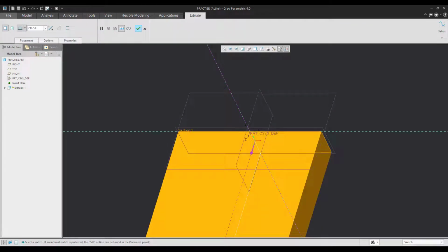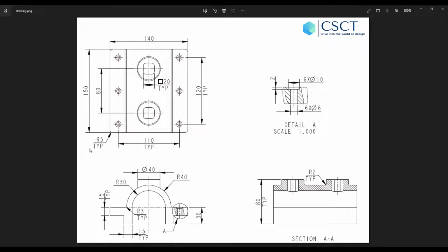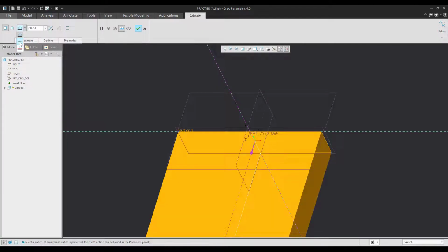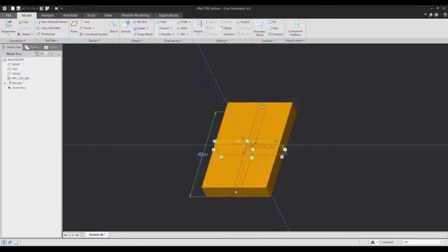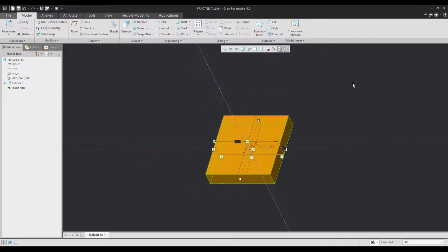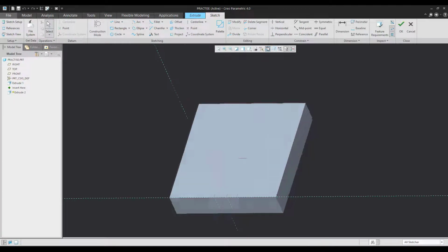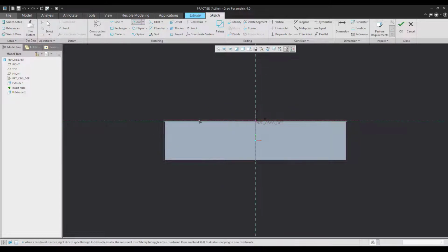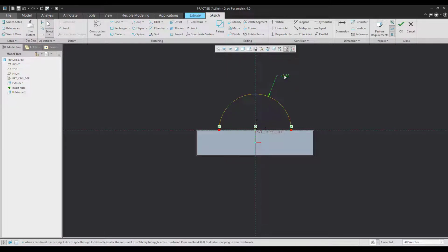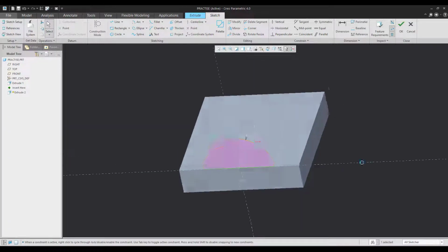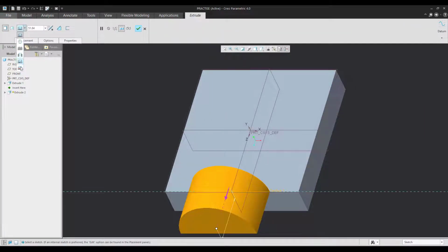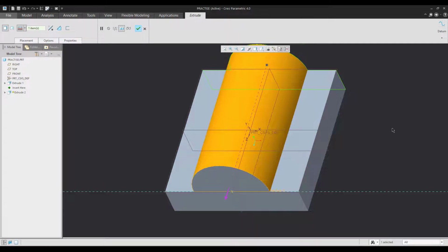Now, the addition of material as per the drawing is done up to 150, in a very symmetrical manner. I'll change this to 150. Now, on top of this, there is an arc which is of 40 radius with this as the center. Let me select the face. I know this is the center and the radius of the arc is supposed to be 40. Since we need it as a solid, I am closing the sketch, creating the extrude up till the selected surface, because I want the extrude only till that particular surface.